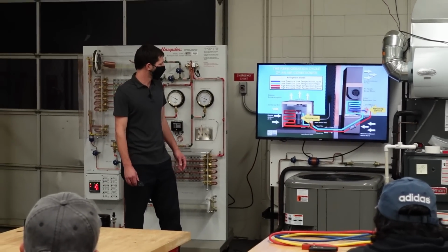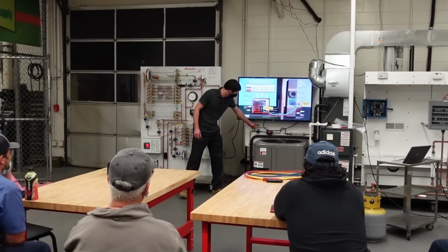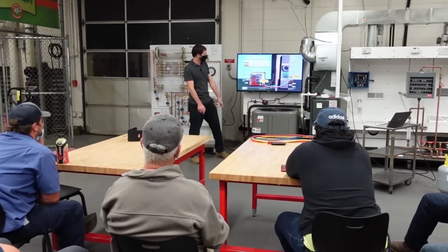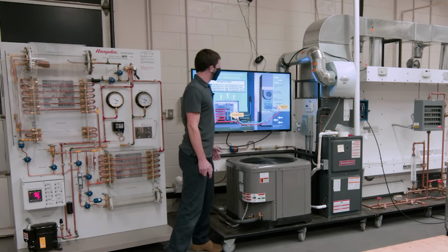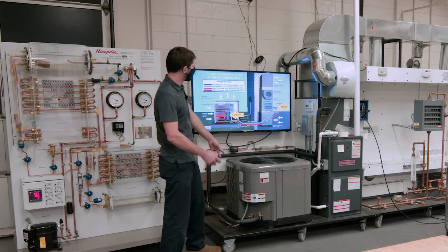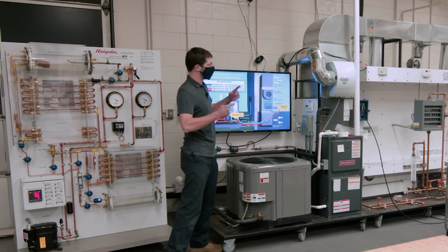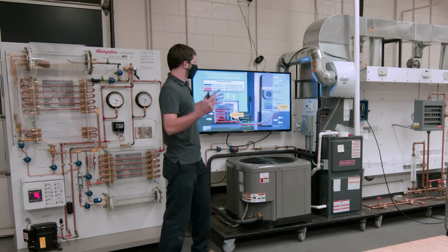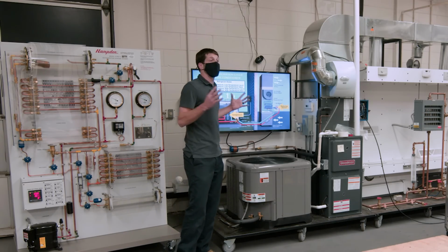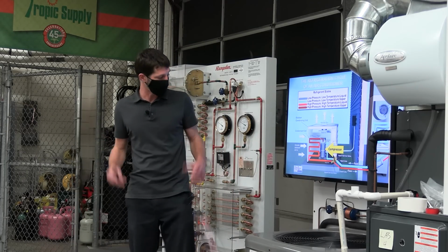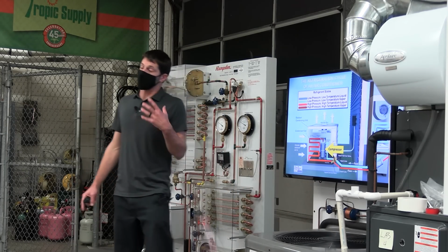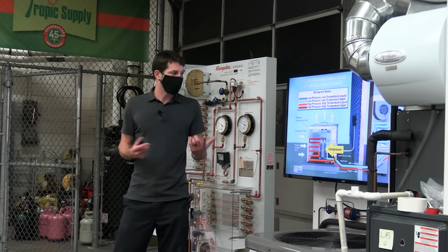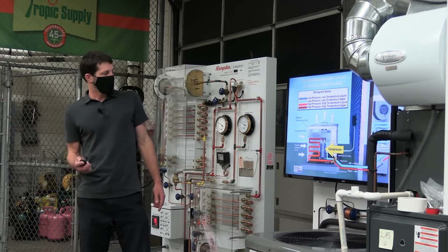They're out there, and so you run into that. That's a fixed orifice metering device. You could run into a piston metering device. Those are both fixed orifices, whereas a thermostatic expansion valve is a lot better for controlling the superheat across the evaporator coil. If you're turning the thermostat on for the first time, it's able to reduce the humidity and reduce the heat load in the building real quickly. Whereas a piston or fixed orifice metering device takes a long time. Like when you need it the most, it's the least effective, right when you're turning it on for the first time. So we'll keep going here.